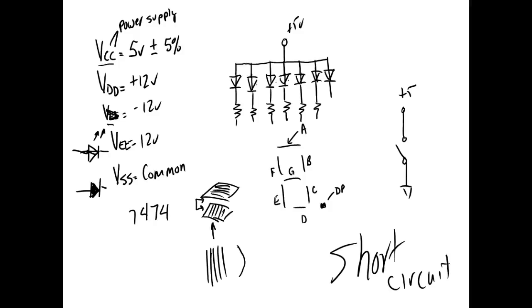So that's liquid crystal right there. But it's still 7 segments. You understand? It's still 7 segment, but it's not light emitting diodes. It's liquid crystal. It just takes a little harder to. And liquid crystals, you got to be careful with them. You don't want to get them real hot because they'll turn black on you. Ever had that happen to you?